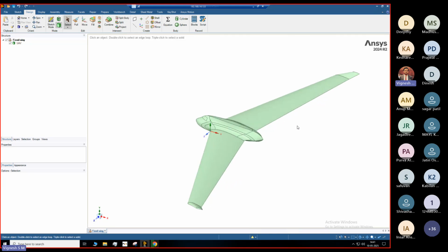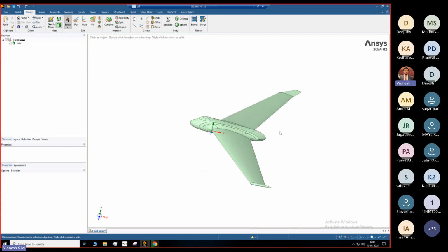So the first thing, as I mentioned, I need to define my goal. My goal over here is that I have modeled one particular aerofoil with a drone. Also, I have a wing to reduce the vortices. I want to know what the weight of this drone is going to be. Aerodynamically, I'm looking for some lift out of it, so I'll make sure I add the respective lift, and I also want to measure the drag. Accordingly, I can also plan the propulsion system for this particular drone. Once the goal is defined, I need to plan a domain.